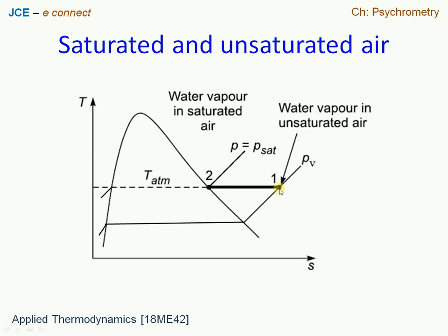That means it is invisible to us, and this vapor is at a pressure called the vapor pressure, the partial pressure of vapor, a lowercase p, in the sample of moist air. When we look at the pressure curves, it becomes very clear that the partial pressure of vapor is lesser compared to its saturation pressure.